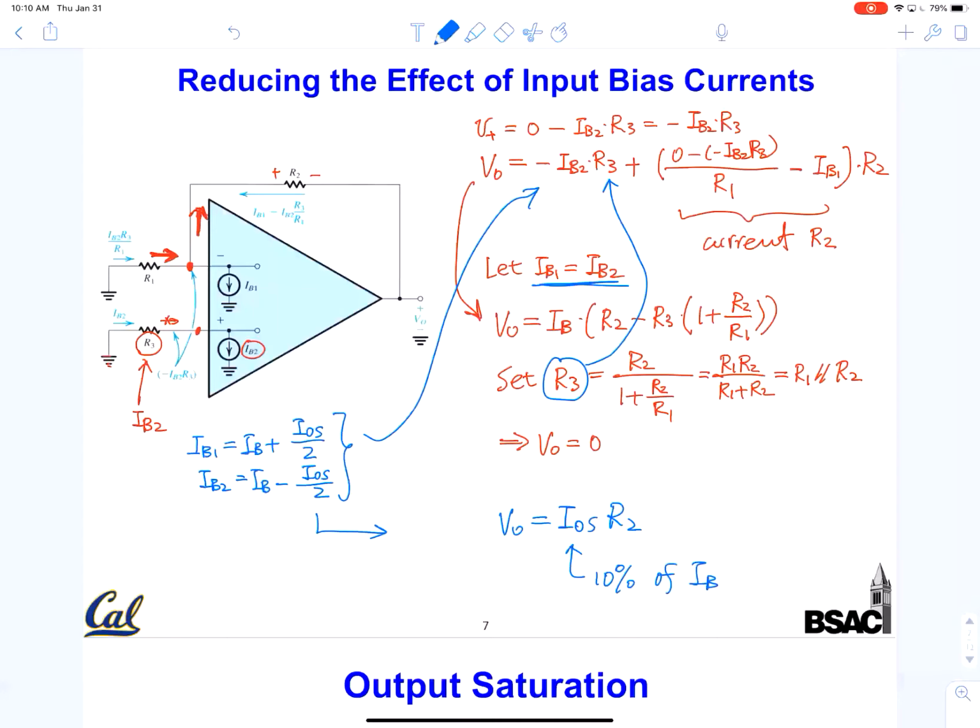These are the circuit tricks to mitigate the non-ideal characteristics of the op-amp. Questions here? So when you look for an op-amp, there are two kinds of op-amp, and you need to look carefully. Some have input bias current, some don't. Okay.